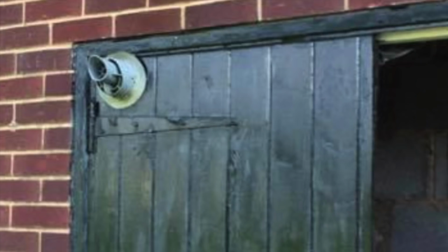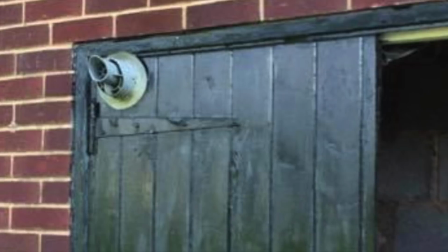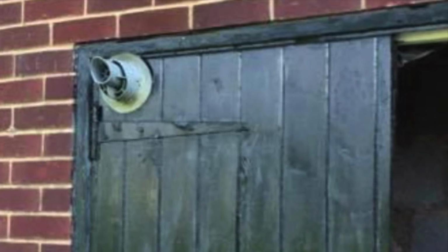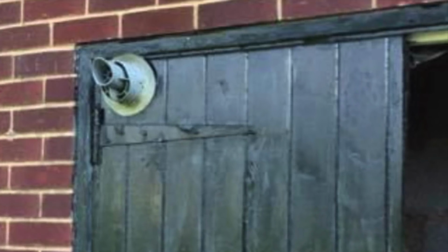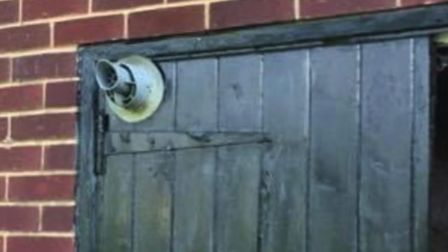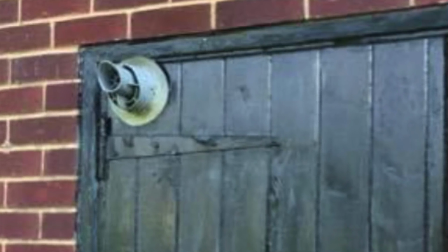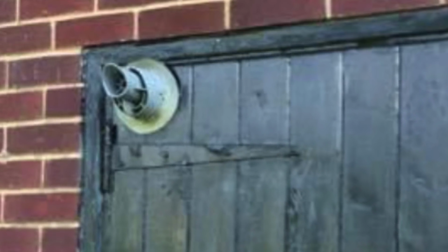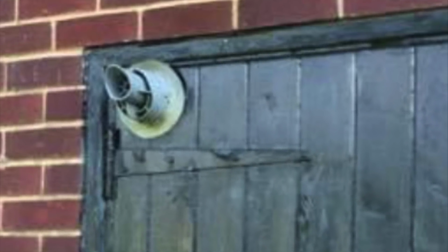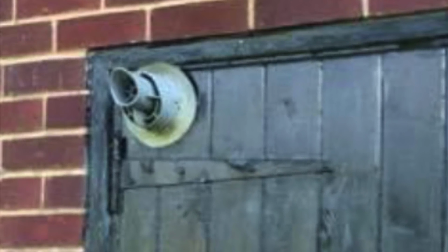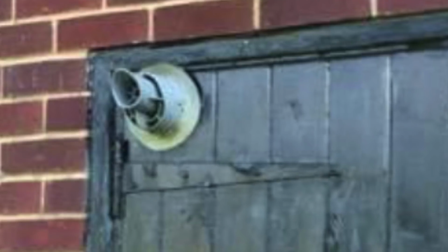We can actually go one step better with this, or is it worse? Anyway, can't say this is the first time I've ever seen a flue like this before. Who'd put a flue through a door? Anyway, this is still an opening into a building even though it's a shed. So if I went out to this boiler, the first thing I would be doing is at-risking it. Who'd actually install this? It just beggars belief.